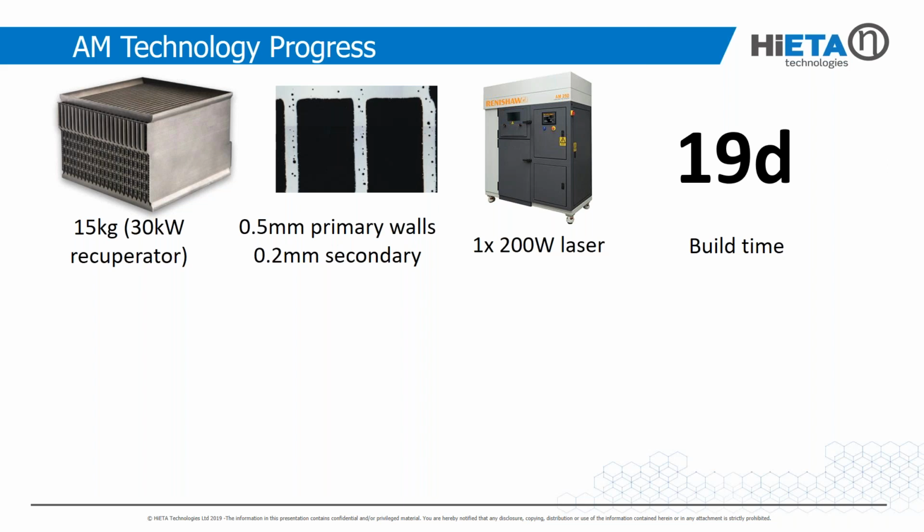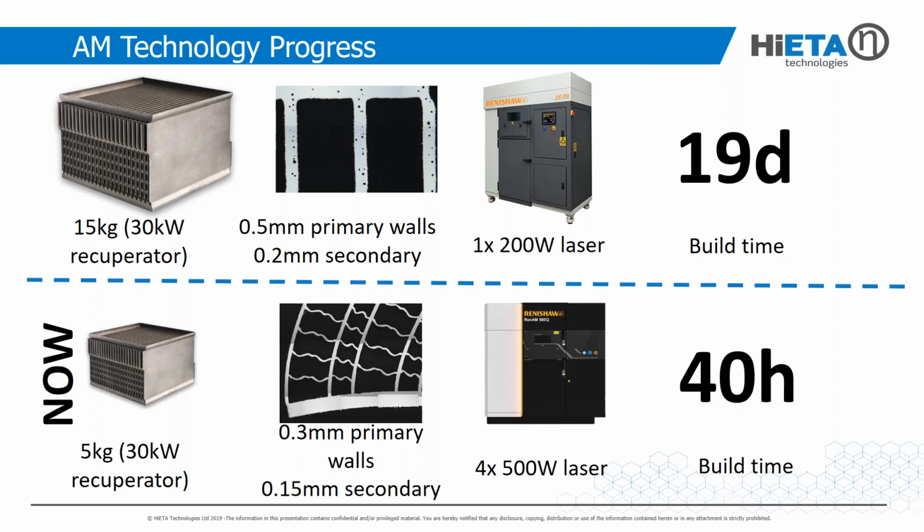You can see the primary walls at 0.5 millimeters with some porosity, and secondaries at 0.2 millimeters. At that time we had only a 200 watt laser machine, just one laser, and the build time of this part was 19 days.